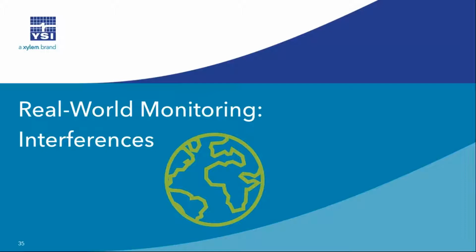Let's do one more really quick before we jump into interferences. Let's see here. So first of all, a lot of folks are asking for that additional information as you promised, so we'll get that out to you guys. As much information as we have on these calibration processes. We have a question from Dan White. He's asking, they ground truth their chlorophyll readings with extraction. So if they're already doing that, they're ground truthing it with extraction, how important are these calibration processes? That is an excellent question. And that's kind of up to you guys. If you feel like the data being generated by the sensor are tight enough with the extraction data you're generating, and you can plot those and see what that slope is, you can do that.